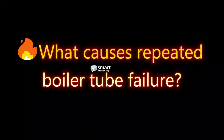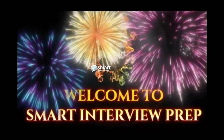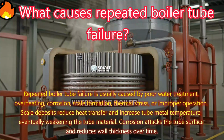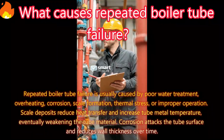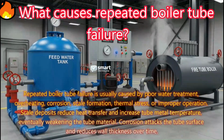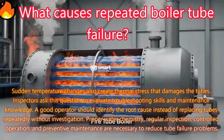What causes repeated boiler tube failure? Answer. Repeated boiler tube failure is usually caused by poor water treatment, overheating, corrosion, scale formation, thermal stress, or improper operation. Scale deposits reduce heat transfer and increase tube metal temperature, eventually weakening the tube material. Corrosion attacks the tube surface and reduces wall thickness. Over time, sudden temperature changes also create thermal stress that damages the tubes.